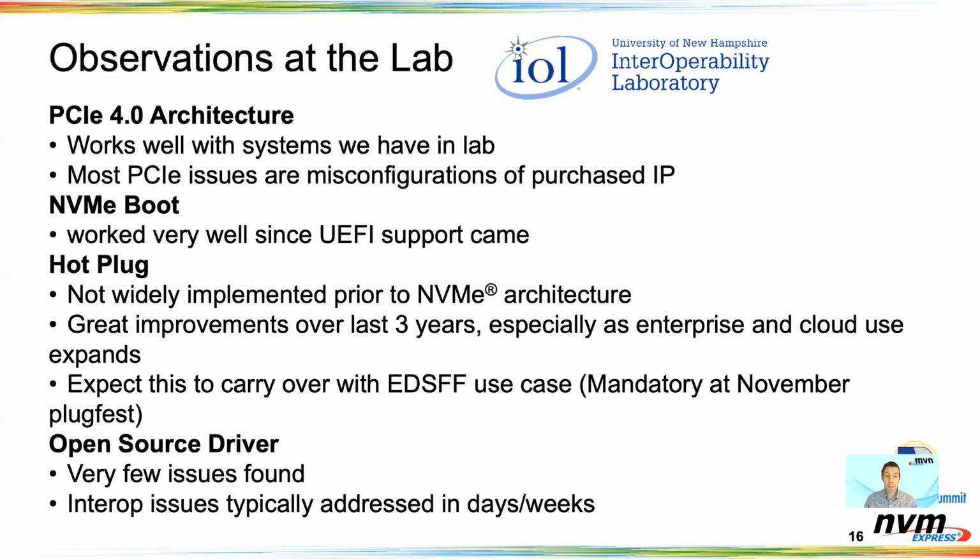Also, with respect to hot plug, hot plug was defined in the PCIe spec, and it wasn't a widely implemented feature, because if you think about a PCIe card, a NIC, or something else being added into a system, it would be very unusual for it to be hot plugged. But on the storage side, you think about a drive being added or removed from an array, that hot plug thing is very important.